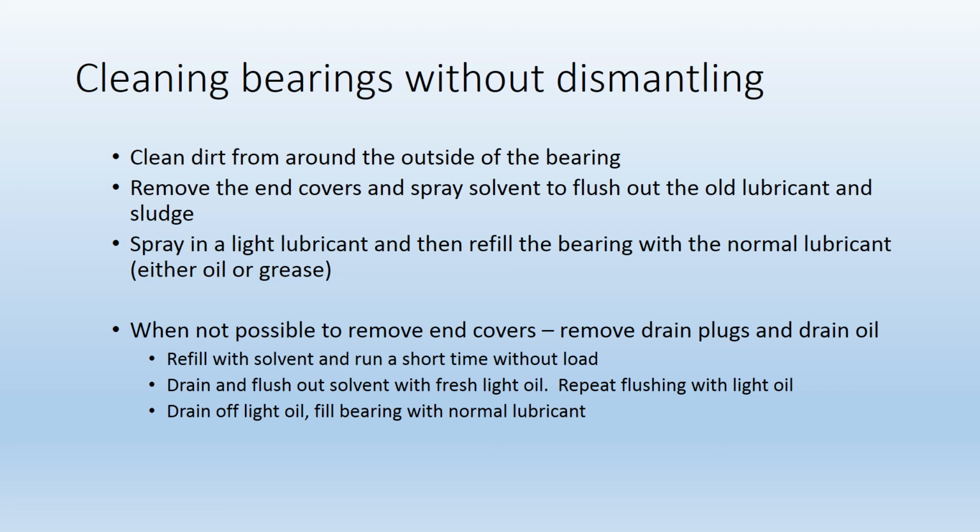and then refill the bearing with your normal lubricant, either oil or grease. When it's not possible to remove the end covers, remove the drain plugs and drain out the oil. Then refill with solvent and run it a short time without any load. Then drain and flush out the solvent with some fresh light oil.